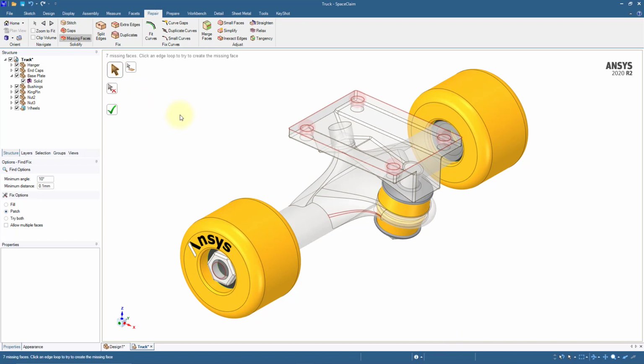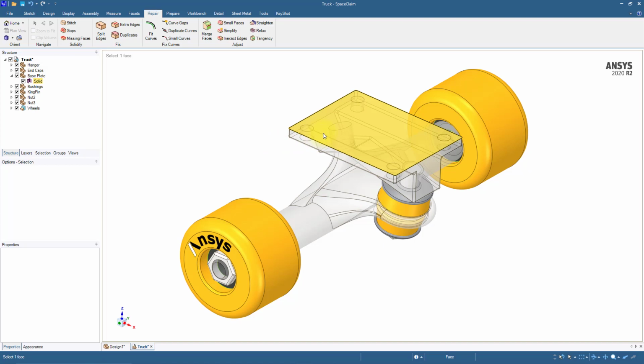Manually clicking individual items that are highlighted allows us to repair them one by one instead of accepting all of them at once. Click the outline of the rectangular face. Once the face has been filled, press Escape. We now have another problem. The new face covers the opening of the 4 holes.